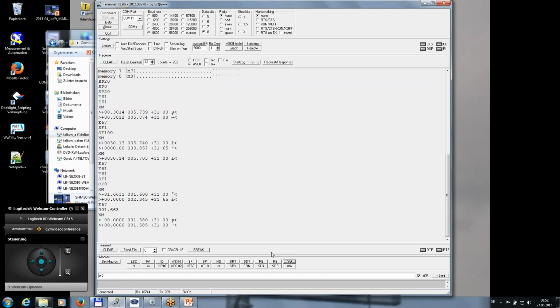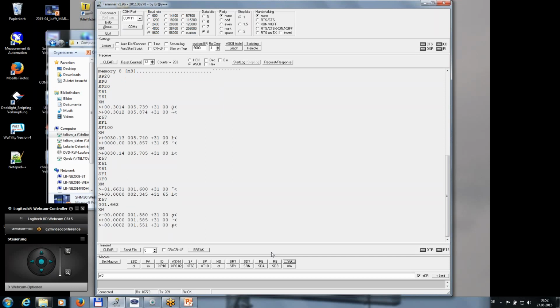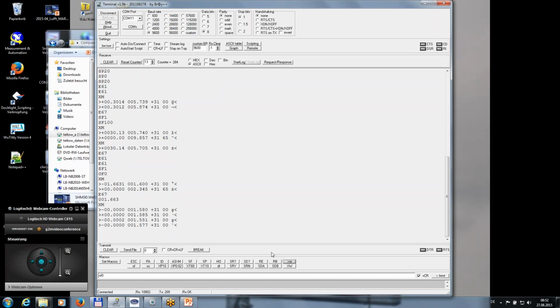Okay, so that's one of the typical steps you have to do. You install the sensor mechanically, you measure the angle, you give this angle inside the sensor with the command SP, then you decide what kind of scale factor you want to use later on, then you do an offset measurement, and after this, in principle, you are ready.